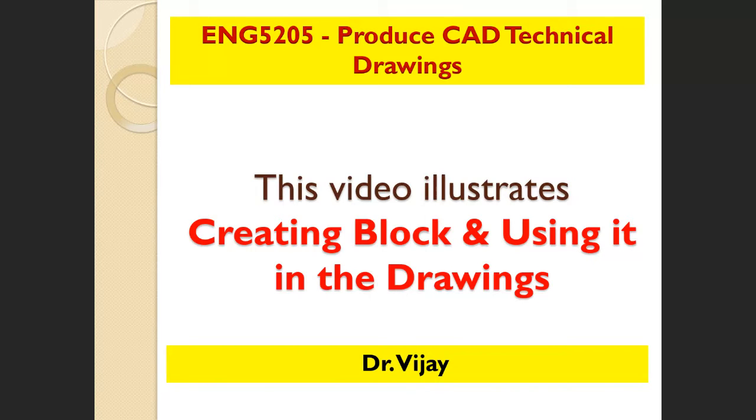I'm Dr. Vijay. In this video, I will explain how to create a block and how to use it in the drawing. Blocks are mainly useful in various drawings. Like in piping layout, we need to insert some wall symbols, and in building drawings, we may need to include many things like doors, windows, and facade, and so many other things as blocks.